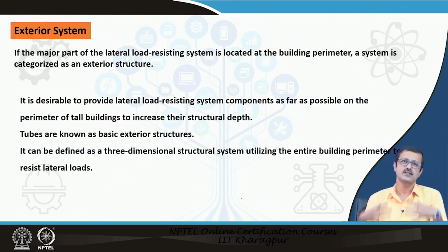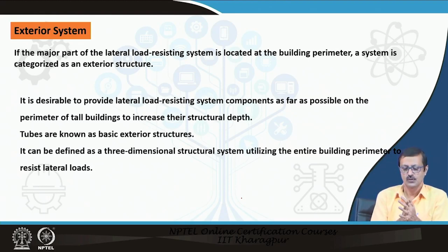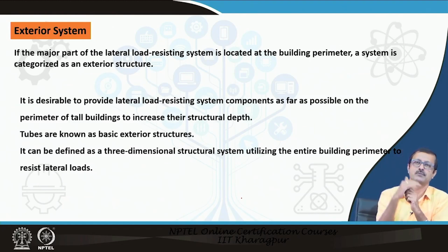See, again you imagine this particular building is a cantilever out from the ground. So, you need to increase the total structural capacity, or the flexural capacity, of the building. It is going to bend because of the load. So, you have to increase the depth. If you remember, in the deflection of the beam we have discussed, the depth increases the moment of inertia I, and that increases the EI, that is the flexural rigidity. So, if I increase the structural depth of the building, I am not talking about non-structural depth, what is going to happen for that?